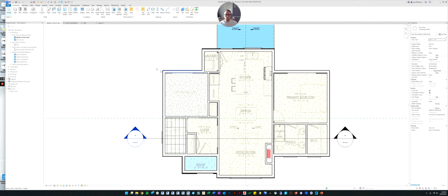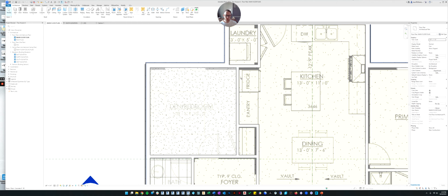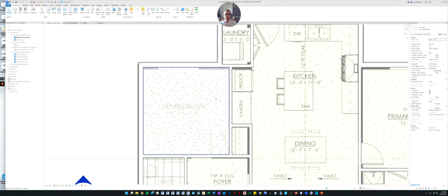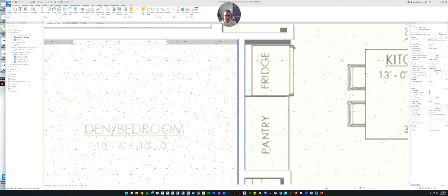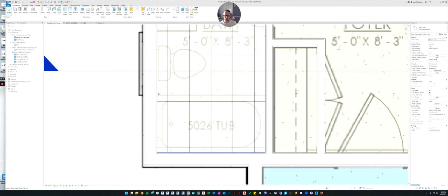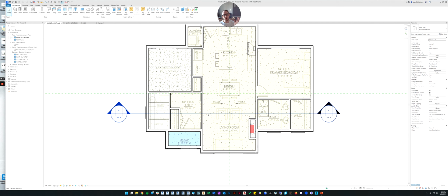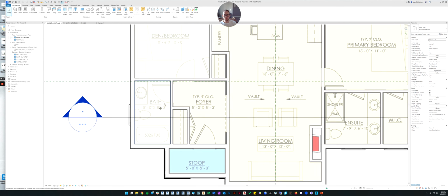You would do the same thing for walls. If you want to put a finish on the wall, instead of recreating this whole wall assembly and adding a layer of tile, it's sometimes nice to create a new wall that's only one layer and only 1/4 inch thick, and you can just assign tile to it, and then you draw the tile in front of the walls that you want it on. So if you were going to put a tile surround around the bathtub, you would create a wall with one layer of tile and you would just draw the wall around the tub. And that's how you would put a finish on the wall. That's how we put the finish on the floor.